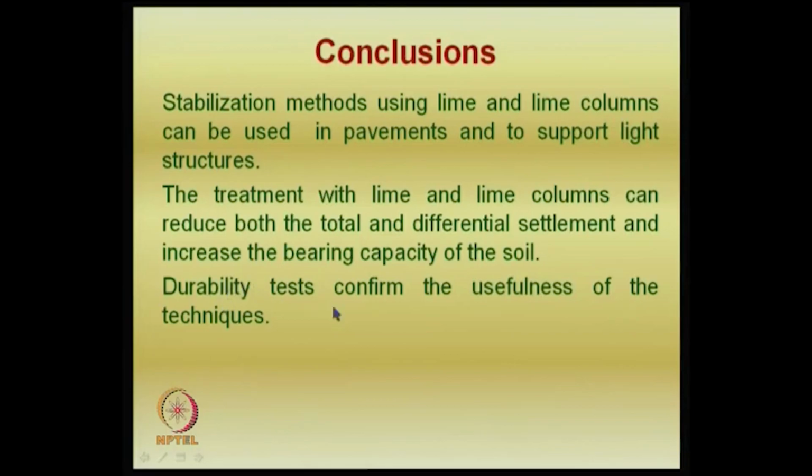Durability tests are also needed. In some cases, where I just showed you, the pavement lasting for about 10 to 15 years was very good. Pavements normally do not last even 6 months, but if a lime treated soil can serve for about 10 years, it is very good. So, what I want to say is that lime is a very useful technique. Lime addition is quite useful.